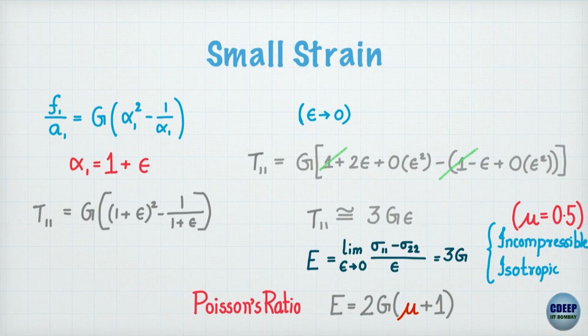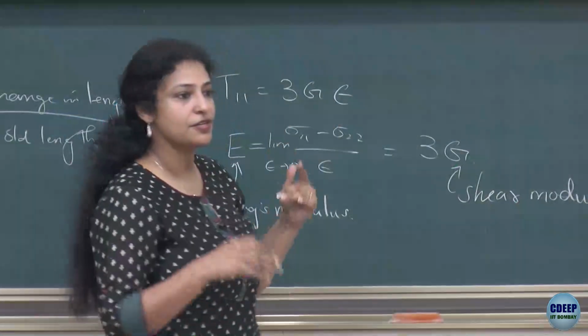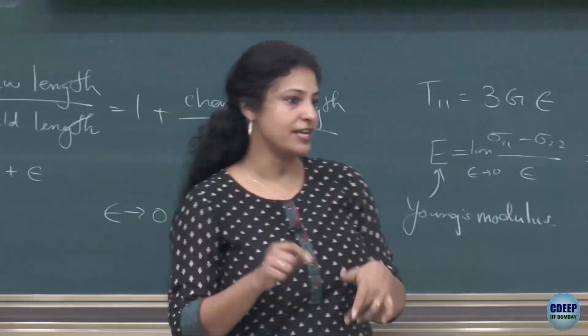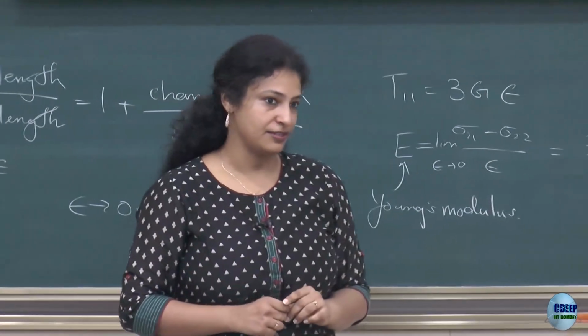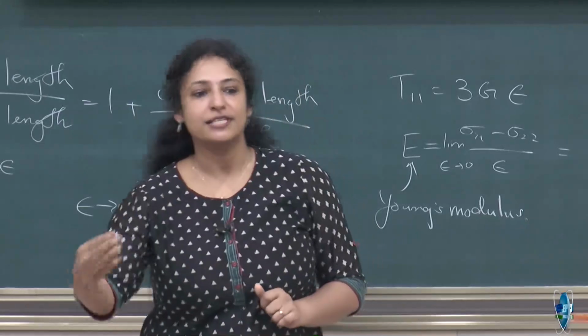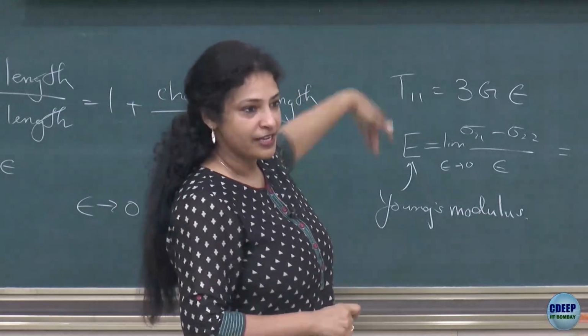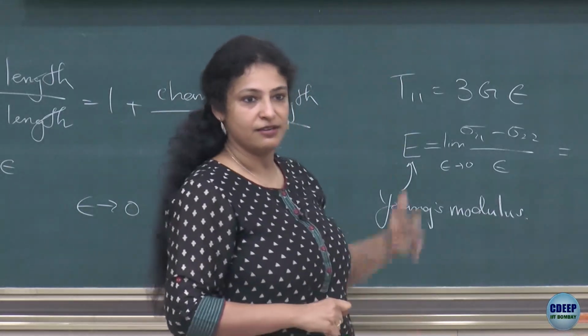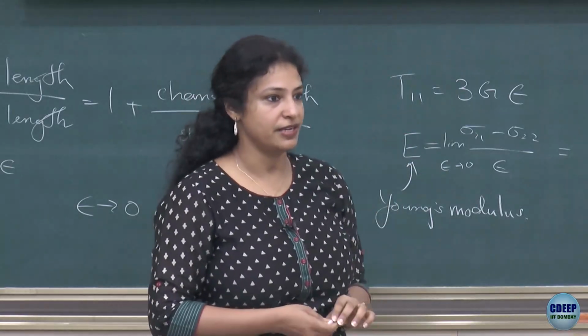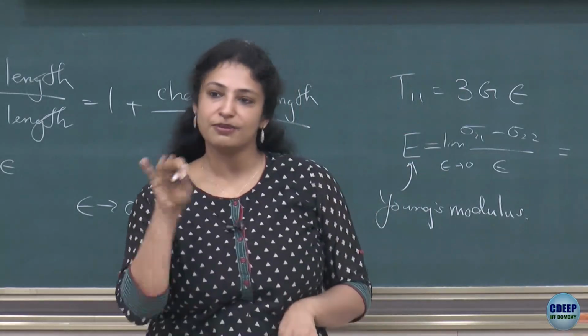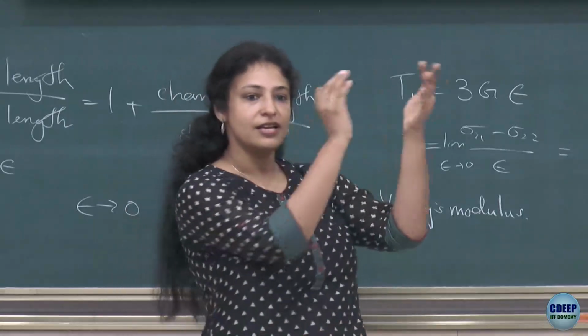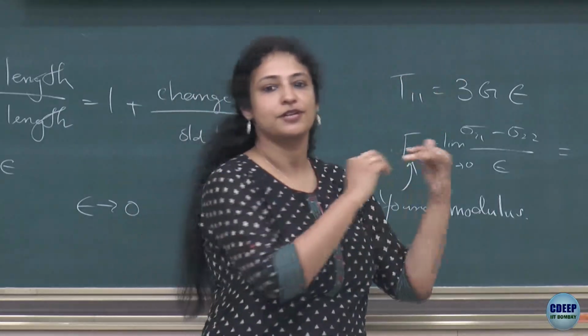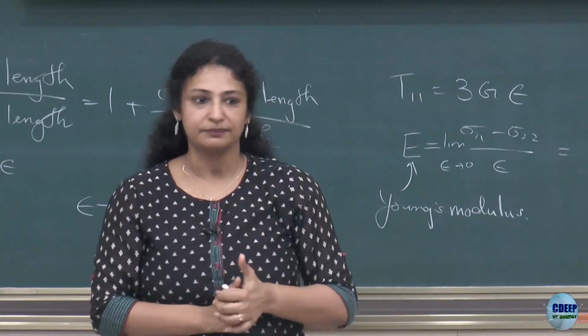But see again, it's a difference in the normal stresses that are appearing, because we'll end up eliminating P, which is the isotropic component, from the equation, right. So, again, why normal stress differences have to be defined slowly becomes apparent as we do these derivations, right. If you remember, the normal stress differences were sigma 11 minus sigma 22 or sigma 22 minus sigma 33.